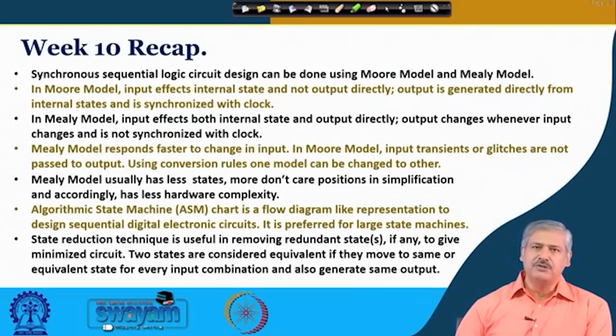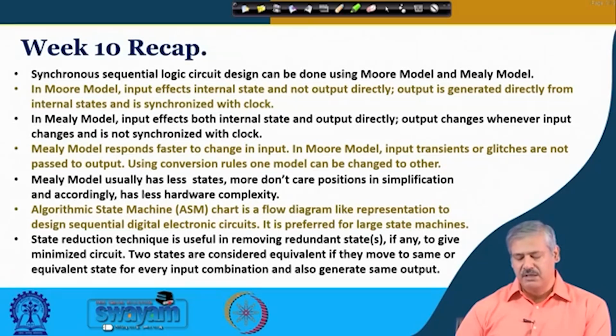You also saw algorithmic state machine chart based design techniques, which is a flow diagram based method. It is preferred for larger state machines because the state transition diagram is found inadequate or very complex to read when the number of variables, number of states, and number of inputs increase.